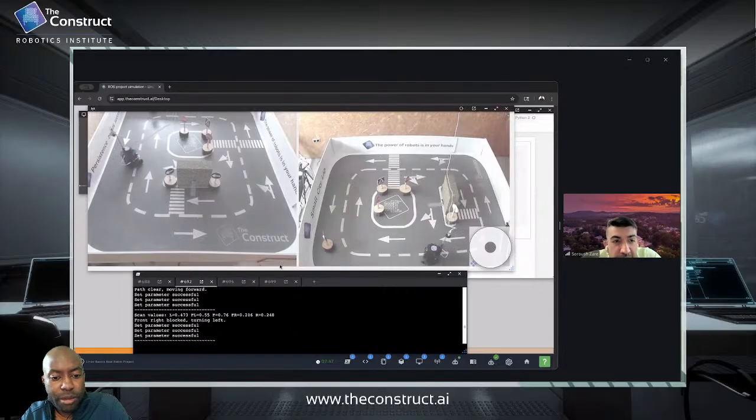So what would happen if you increase the number of sectors that it has to take into consideration? What do you mean by the number of sectors? At the moment, the area around the robot is being split into how many? You're taking into consideration 8 laser scan ranges, is that right? Yes. What would happen if you used, let's say, 16? Oh, okay. So then we have, for example, 16 conditions.